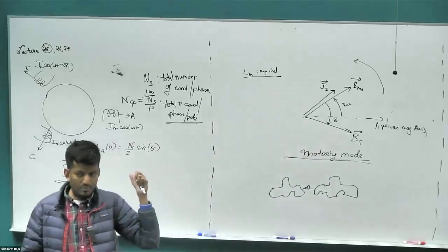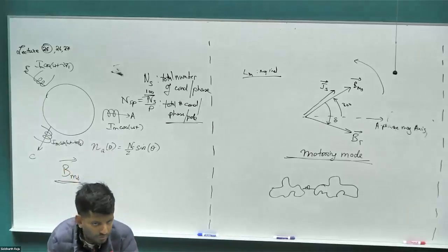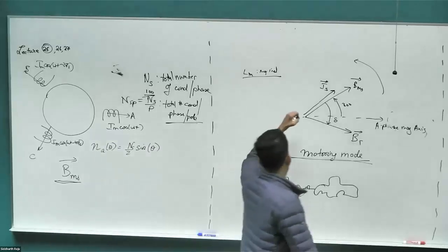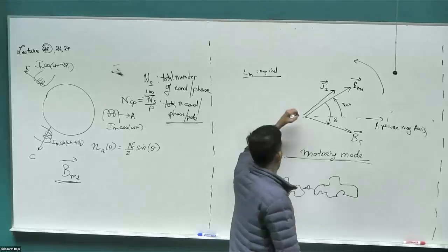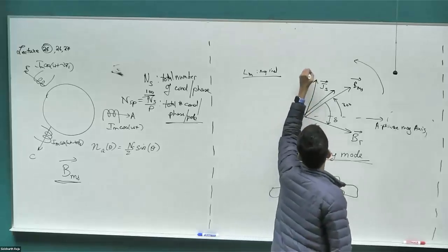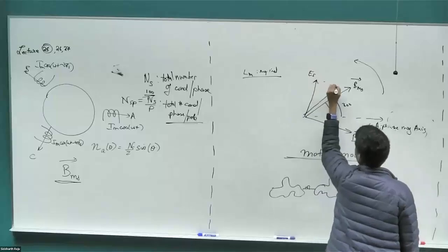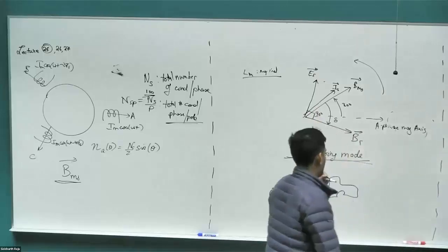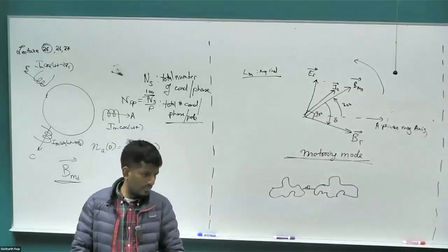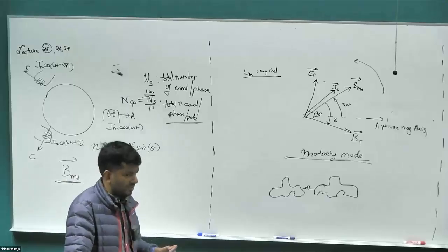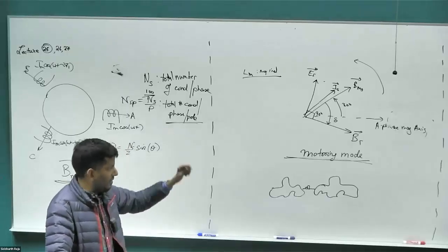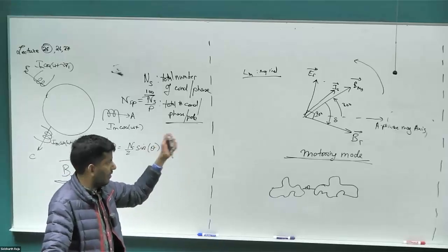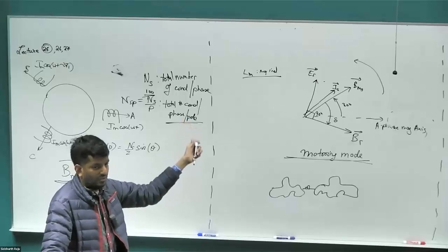What will be the direction of the EMF of the rotor magnetic field? The ES space vector is going to be 90 degrees ahead of the rotor magnetic field. Why is it 90 degrees ahead? What relationship did you use to figure that out? We can calculate the EMF for each of those phases, which was the homework problem. Take that EMF, plug it into the space vector transformation, and it will tell you that it's clearly 90 degrees ahead. But there's a much easier way.